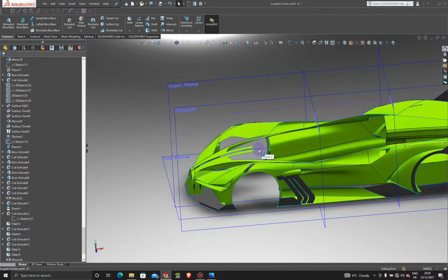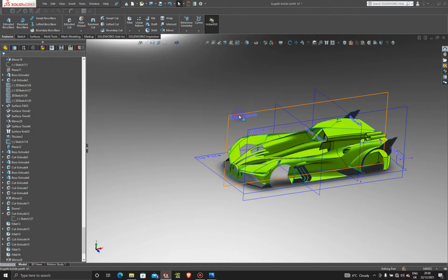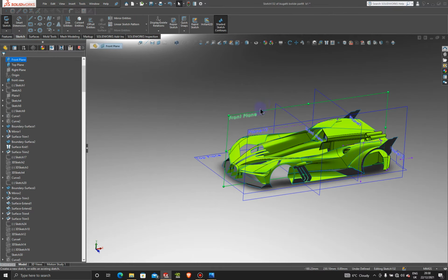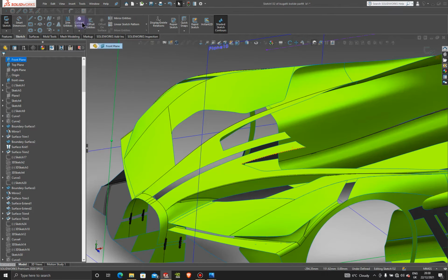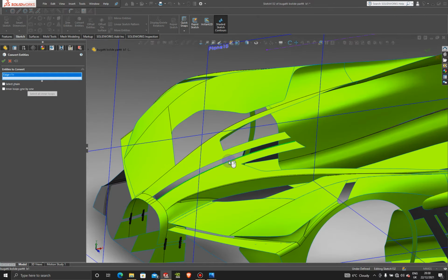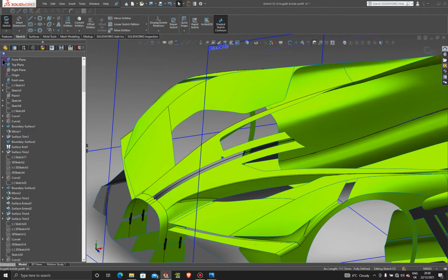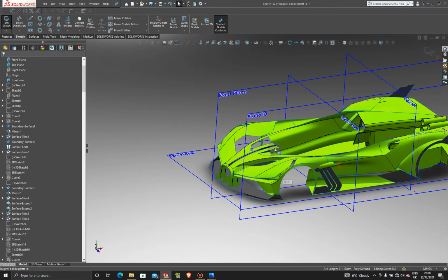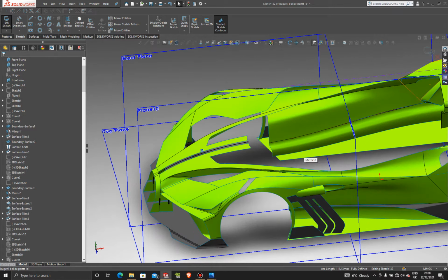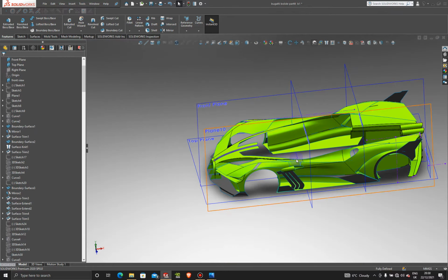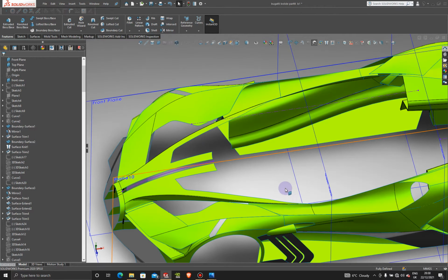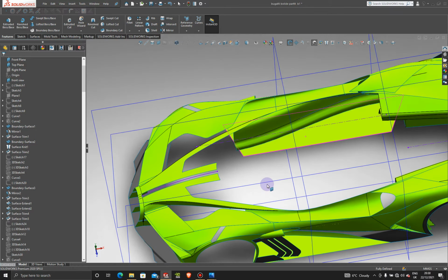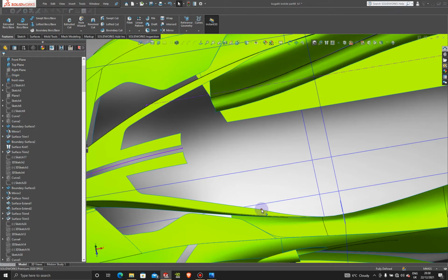So what we're going to do is create a sketch on the front plane, okay, and then we're going to convert this edge here. Press OK, and that drops a perfect perpendicular line right in the midsection. All right, so exit the sketch. And if you've been following my tutorial step by step the way I'm doing it, you should have all the edges and corners that I'm having, so you shouldn't have any problems.